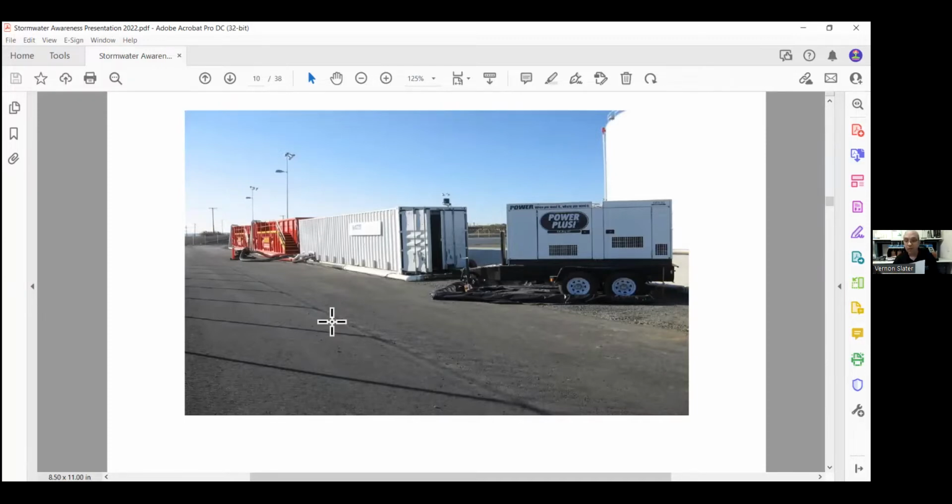These systems differ from active treatment systems in that they will use settling, mechanical filtration, and specialty medias in place of chemicals. However, at times, the turbidity level of the water flowing to the dewatering system may need removal before the specialty media or to meet local discharge requirements. In that case, the dewatering system will become active in the fact that chemicals will be applied to reduce suspended solids. In this case, residual requirements will need to be met.